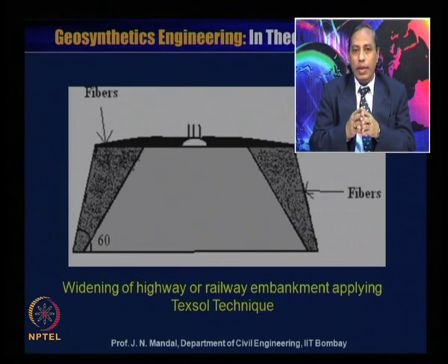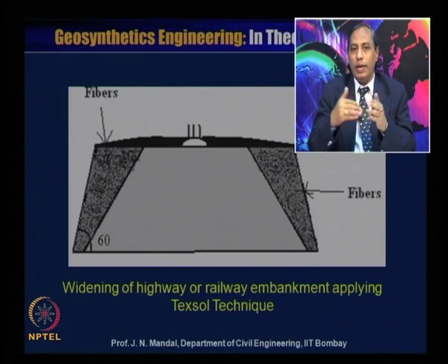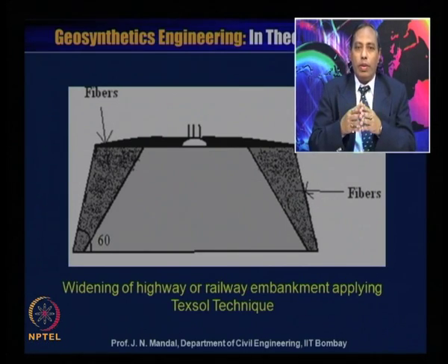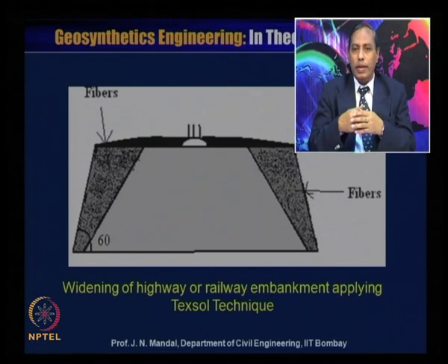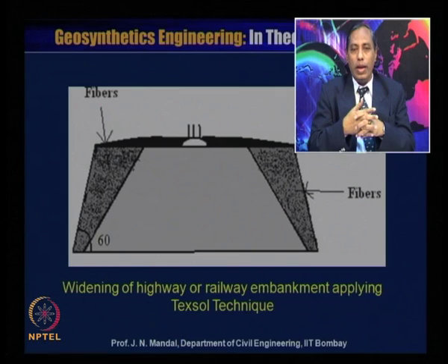Apart from that, you can use this kind of fiber soil mixture, and you can place it for widening the road. It is also very stable. We have performed many laboratory tests using different percentages of the fiber element, and we found very encouraging results.